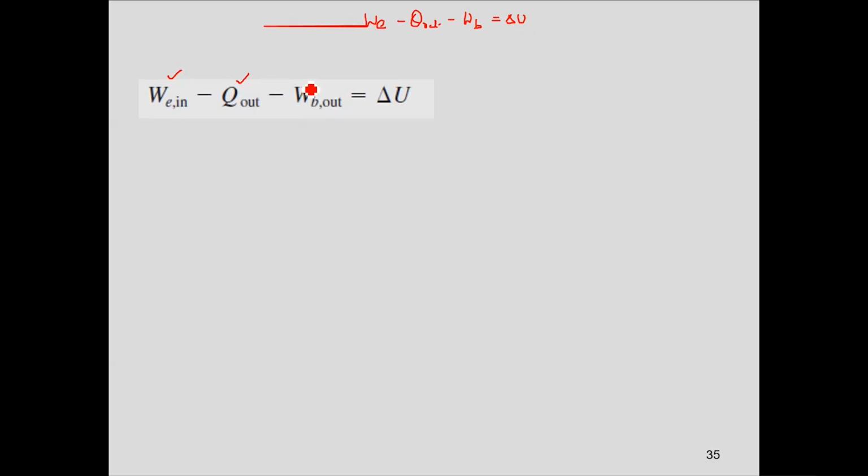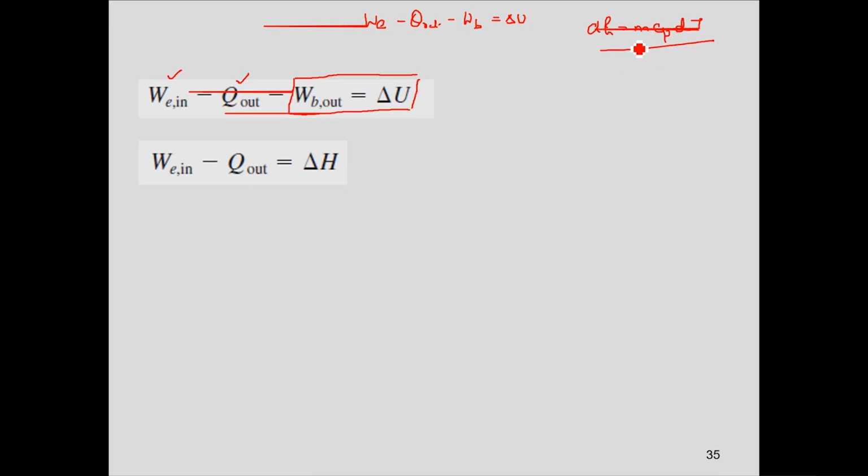You already know from your knowledge that for a system which is undergoing a constant pressure expansion or compression, you can combine boundary work and delta U with delta H. And delta H, if you remember, dH is essentially mCp dT. This is dH. So if we have m(H2 minus H1), which is dH, dH can be replaced by Cp (T2 minus T1). Mass is already there.